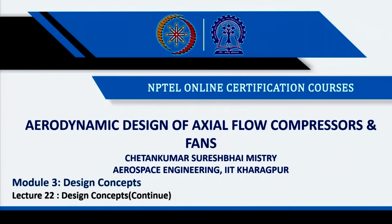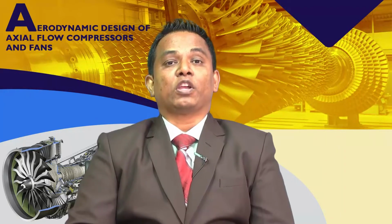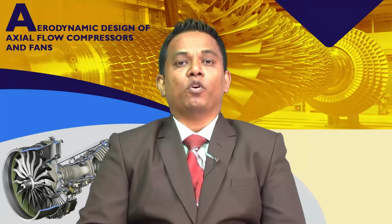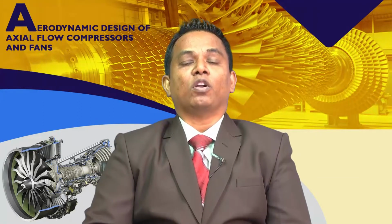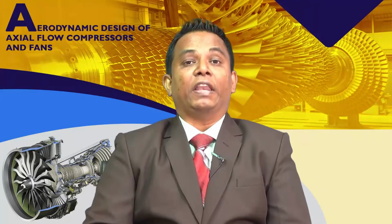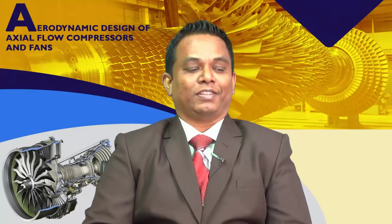In the last lecture we were solving a numerical, to calculate the variation of flow angle by considering free vortex configuration and constant reaction configuration. Today let's take one more numerical, based on the free vortex and exponential kind of swirl distribution. That will give you some other kind of feeling in understanding the methods or design concepts we have discussed in the past few lectures.